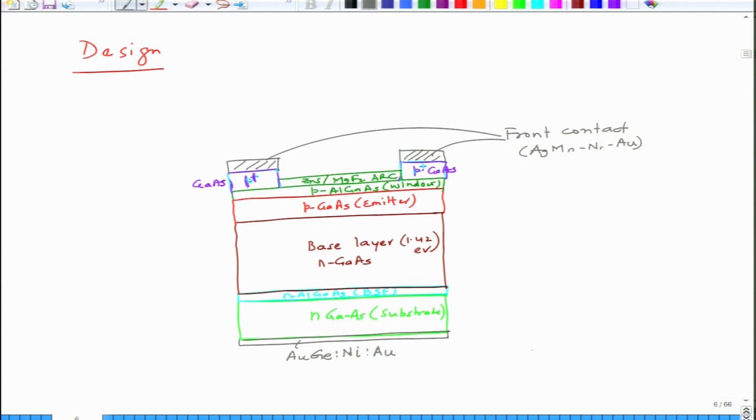So, you put in all these layers together so that you make a good contact, all right. So, again the work function matching has to be done so that carriers are not blocked by the electrodes, but again similar concept for the electrode. You can't cover the whole surface with the electrode because of opaque nature of metal. So, as a result you have to optimize the electrode position just like you did in silicon.